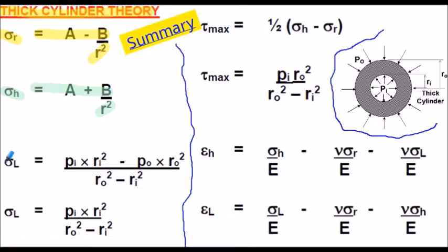We've got two formulae here for longitudinal stress. The first one has an internal and an external pressure applied to the vessel, but the second one just has an internal pressure. The external pressure is assumed 0. And remember, we're always using gauge pressures here. And later questions may want us to calculate the maximum shear stress in the vessel wall. And again, we've got two equations we derived previously to calculate the maximum shear stress in the pressure wall.